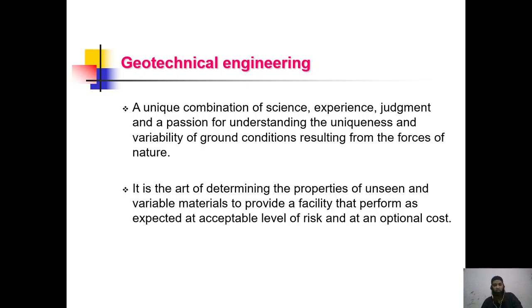It is the art of determining the properties of unseen and variable materials to provide a facility that performs as expected at an acceptable level of risk and at an optimal cost. Basically, we have to know the different types of properties that soil contains. If the properties are not up to the requirement of withstanding the loads, then we'll have to go for some treatments to increase the load bearing capacity of the soil. So even this is needed well in advance.